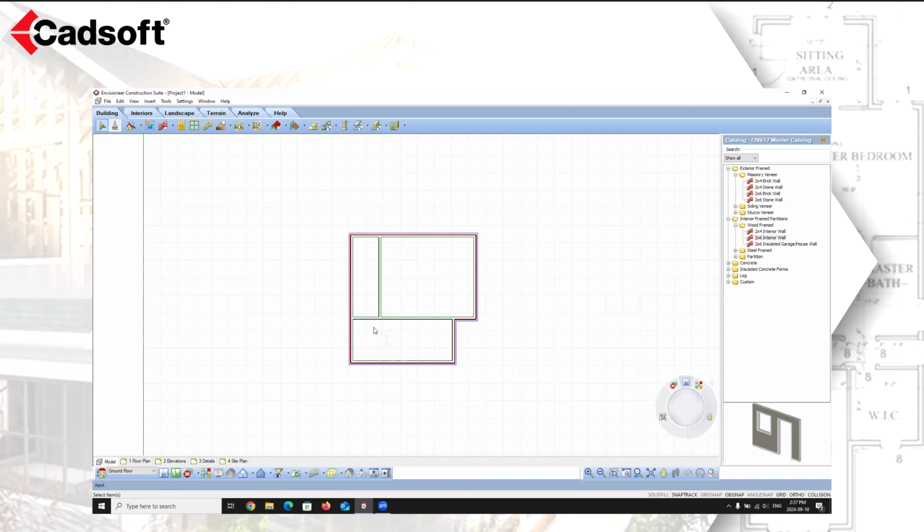What we're going to do now is look at creating a wall using the copy option. So walls can also be copied to create new walls. You can click and drag the copy to a new position, or you can use the commander to specify a precise move distance and a direction. So what we're going to do now is select a new wall. We're going to select this wall right here.